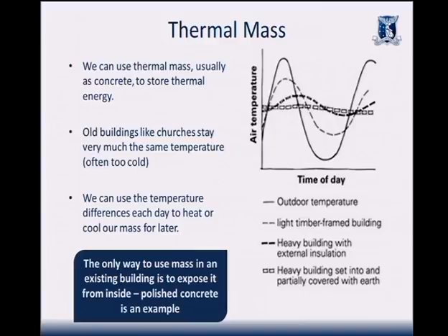It's going to sit at the average temperature of the outside air. So it will average that temperature. And what you're seeing there is the thicker dotted line, the hollow one, is the average of the fluctuating outside temperature. So it's storing heat and releasing it to stabilise the temperature.